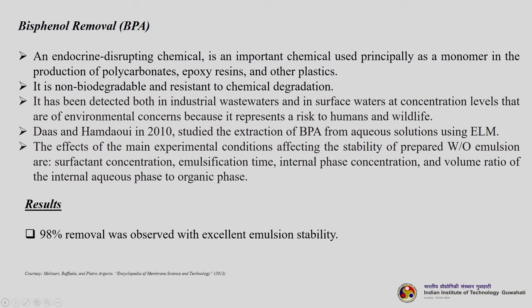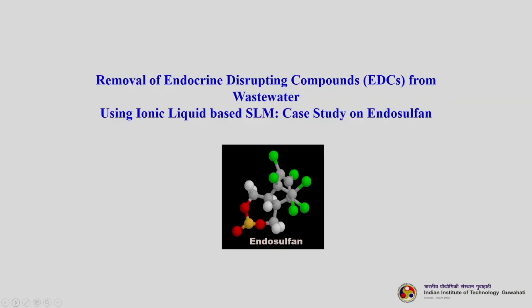Das and Hamarawi in 2010 studied the extraction of BPA from aqueous solution using an ELM. The main experimental conditions affecting the stability of the prepared oil water emulsion are surfactant concentration, emulsification time, internal phase concentration, and volume ratio of the internal phase to the organic phase. 98% removal was observed with excellent emulsion stability. So, very quickly I will show you one of the case studies which was done by one of my PhD students, Dr. Santhiraju Pilli.